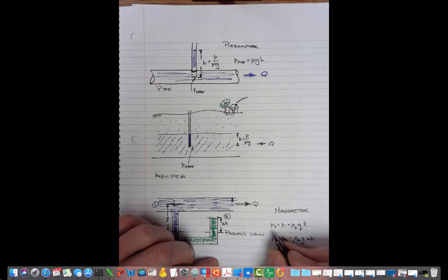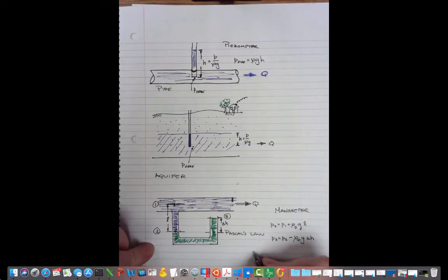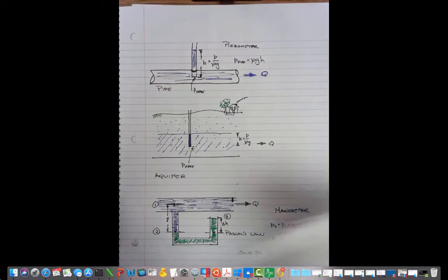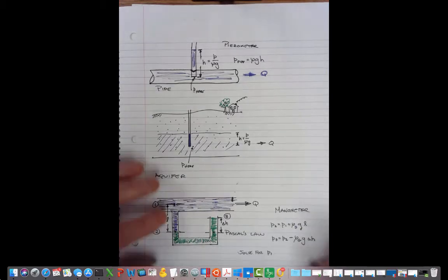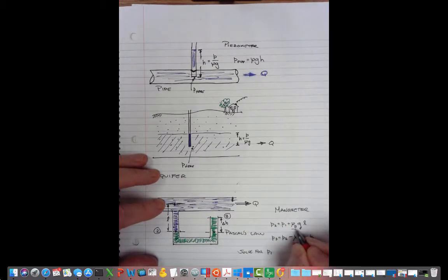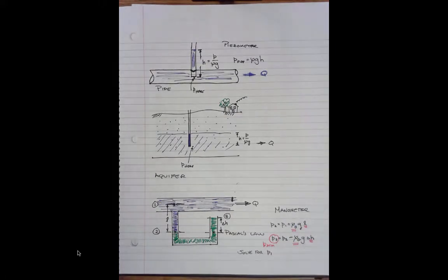And so we can now substitute the various equations into each other and solve for P1, which is normally what we're after. What we'll need to know is what the densities of the fluids are, and we need to measure the L and the delta H. And then P3 would be atmospheric. And with that, we have everything we need to find the unknown at P1.